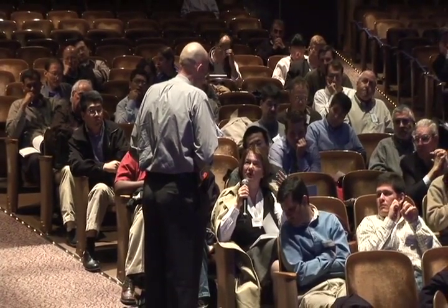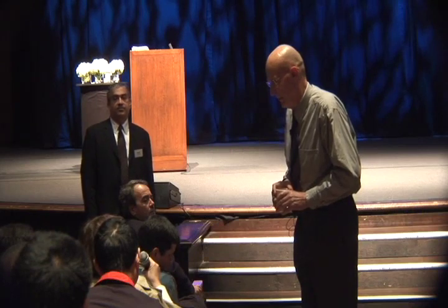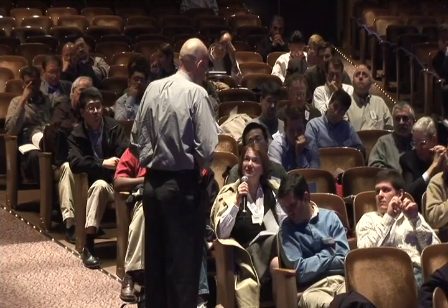There you go. You emphasize that it's very important to properly treat P delta effects. And I'm just wondering, do you have to do something special to really model them properly in the analysis? Because from my experience, often you would have moment-resisting frames coupled with some gravity columns, and it's really the moment-resisting frames that are taking care of the overall sway effect that causes additional P delta effects. But often what I find in programs is that the tributary gravity loads affecting these effects are not adequately treated. So I was just wondering, how do you go about it in Perform?